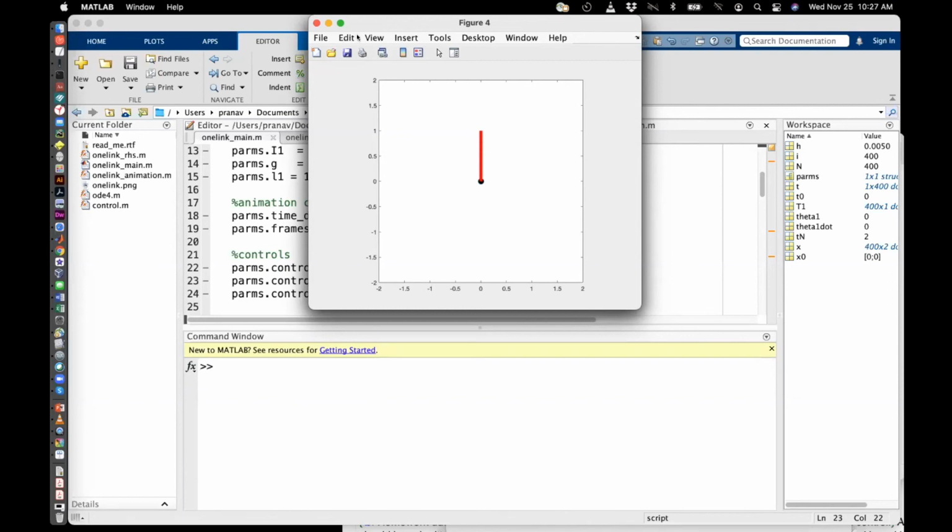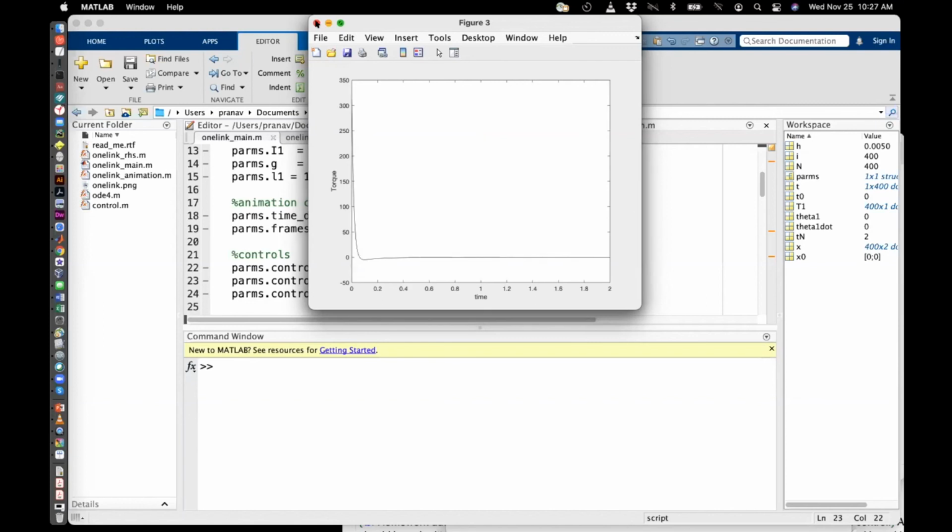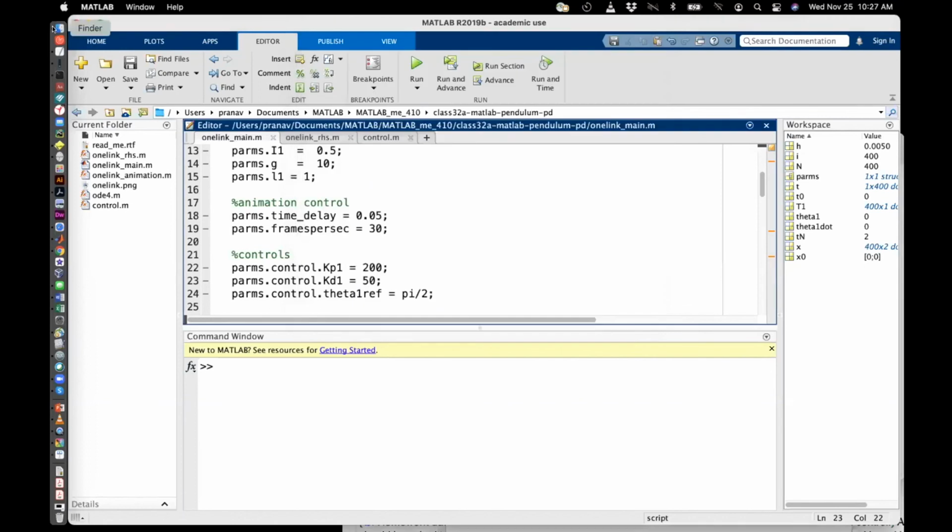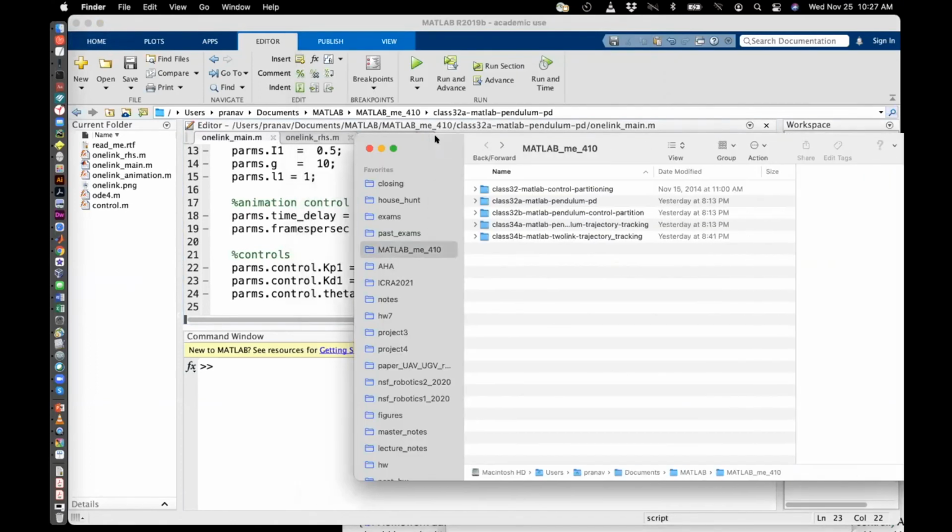And then it stopped. So let me close this. The torque, this is the velocity. But look at the position. You can see that it's going from 0 all the way to 1.57. There's no overshoot, and it's settling in about 1.6 seconds. Okay, that's something you want to remember. 1.6 seconds, and I got it fairly easy by just tuning numbers 2 or 3 times. But if you have a more complex system, more than one link, then it's clearly hard to do this tuning manually.